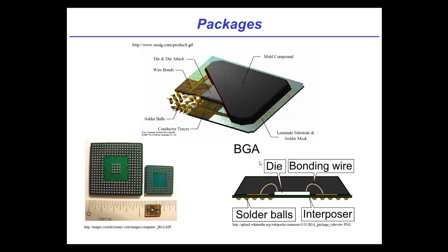That's right. So the package is actually the outer surrounding on the chip, and it encapsulates the chip itself as well as the various package interconnections that we talked about before. So Michelle already pointed out that there can be wire bonds on the inside that go from the chip to the outer substrate. There are other types of packages that exist as well. So for example, this is a ball grid array where rather than using wire bond, the chip is actually flipped over and little balls of solder are placed between the chip and the substrate to make connections. Then the whole thing is put inside some sort of protective case, typically some sort of epoxy or black plastic, and that's what we buy when we buy chips. And what has that given us, all said and done?